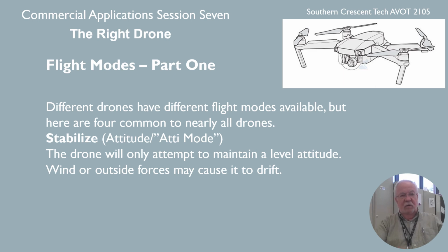There are certain atmospheric conditions or locations outdoors where there might be confused GPS signals, close to a bunch of large buildings might block the signals. So you'd want to do this. We'd want to turn it on ATTI mode so you wouldn't get some false signal that would cause the drone to act erratically.